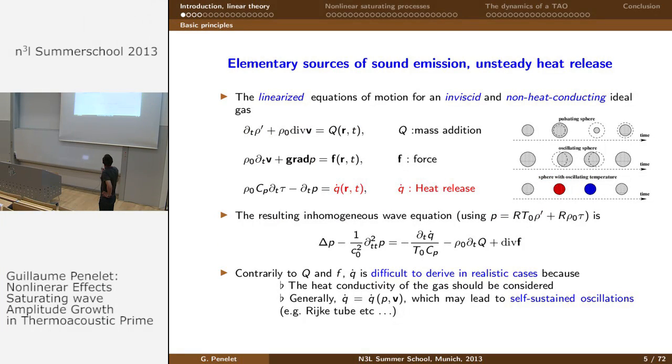Okay, so let's begin with the first part of my talk. So, as all of you know, there exist 3 elementary sources of sound emission in acoustics, which are associated to 3 conservation equations, which are the continuity equation, the momentum equation, and the energy equation. So when making thermoacoustics, we are interested in this last equation, so sound emission by unsteady heat release. And it's worth mentioning that such a problem is generally more complicated than a sound emission, for instance, by a pulsating sphere, because mainly for 2 reasons.